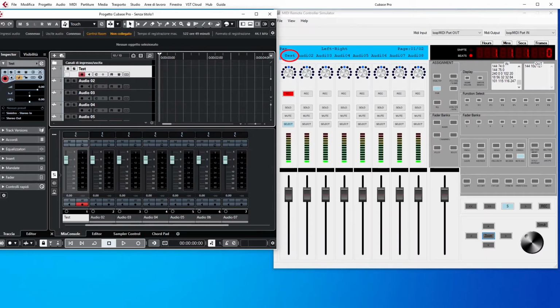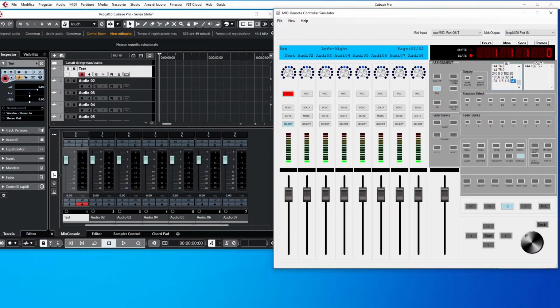You can see in the input area here the System Exclusive MIDI message that arrived for the LCD main display. There are the opening and closing bytes F0 and F7. There is the position of the text here at the 56th character. The 56th character is the first character of the second line. There are two spaces here that you can see. Then the capital T, E, X, T, lowercase.